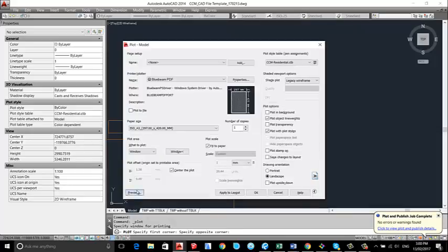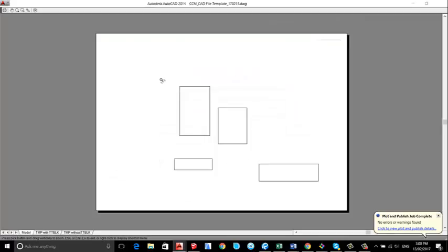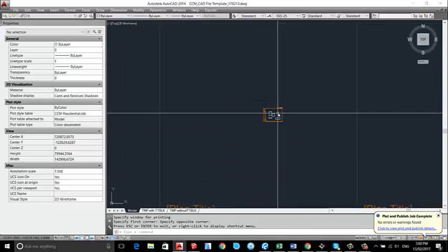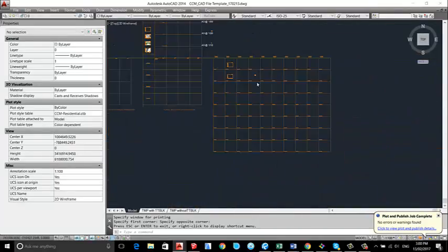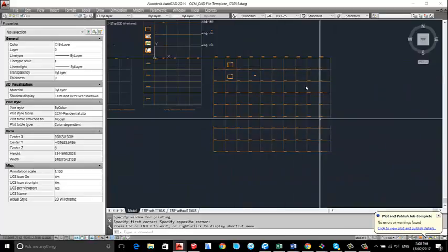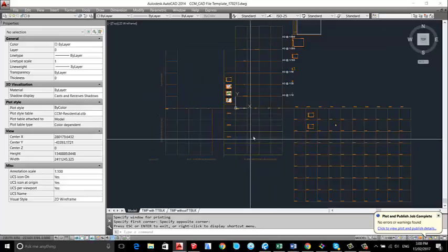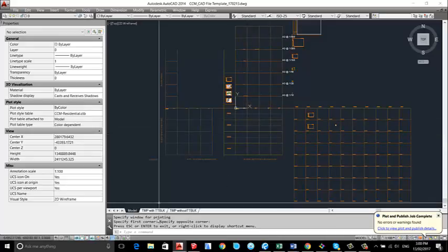select this. Now this will come in position, so when we add the titles and everything in Bluebeam or in another PDF program, it will fit in position. So yeah, there are these two ways of printing. One is having the page on this area, or we just do the drawing, like the plans and the elevations, and printing from the viewport, or any combination from there.